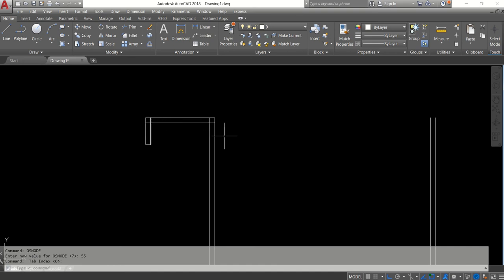This time I want some radius over here. So I'll give the command fillet, and this time I'll give some radius. I'll hit R, right? I can click on this radius or I can hit R and spacebar. What radius do I want? Now the thickness is 3, so let me give a radius of say 1.5 and hit enter. Now what happens? I'll select this first point and select the second point.